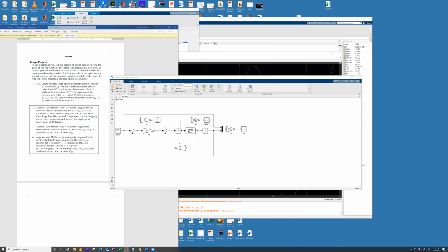If you really want to be looking at how to tune, then you can add a non-zero disturbance and try to tune the PID gains. But when you have disturbance, external disturbance, you need additional schemes to come up with good PID gains. But you are welcome to add disturbance and then see if your system is working or not.